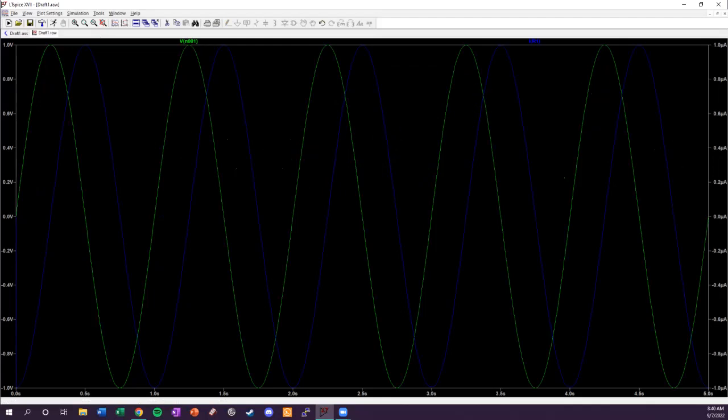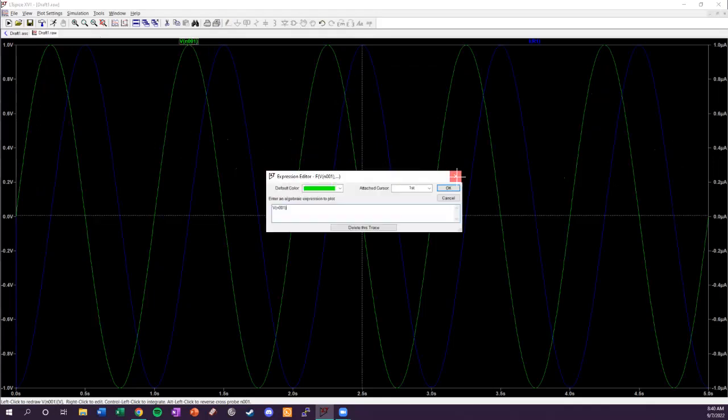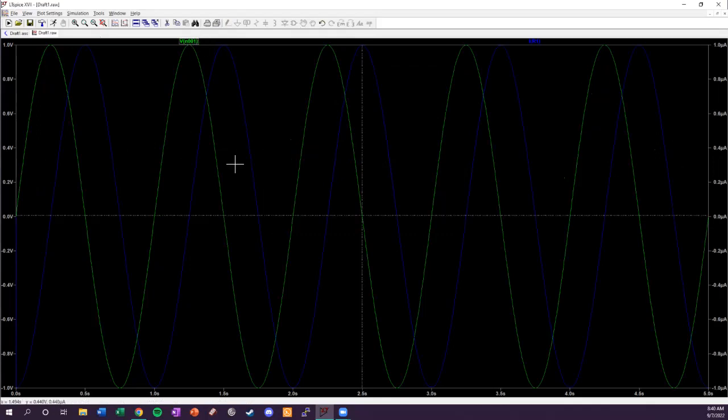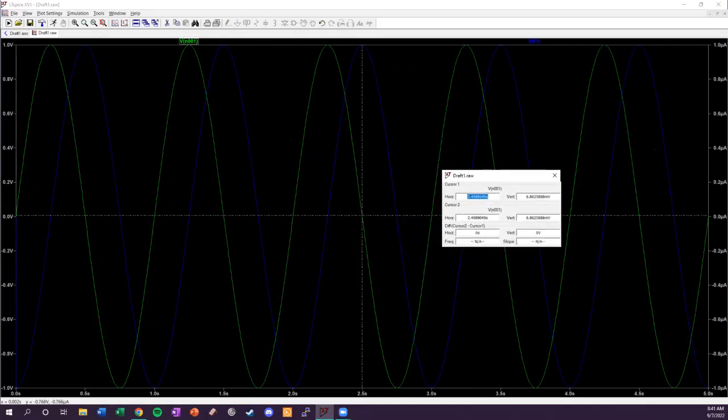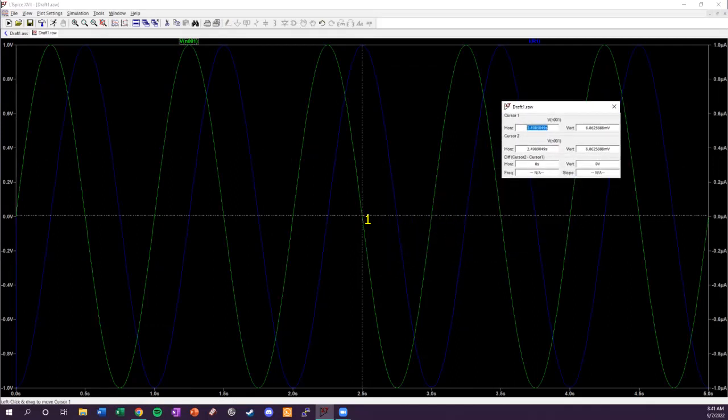So here you can see current in the blue line, voltage in the green line. If you wanted to actually measure specific points, what you would do is click the title. Nope, I right-clicked it, don't do that. I would click the title, and then here, you would see this little screen over here. And then you can move this cursor around to follow the actual traces. And you can see the voltage at specific points in time. This is true regardless of what simulation you run, and we're going to go over this again at some point.